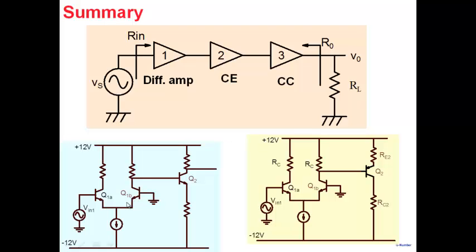Remember that we had designed this differential pair with the highest possible gain, but this stage didn't give us gain. So we had to go back and lower the gain of this one, make it deliberately bad, so that this stage can improve and the overall gain of the amplifier improves. I'm not claiming that 1000 is the highest gain you can get. If you sit down and optimize further, you may be able to push the gain further. I just gave you a sample design there.